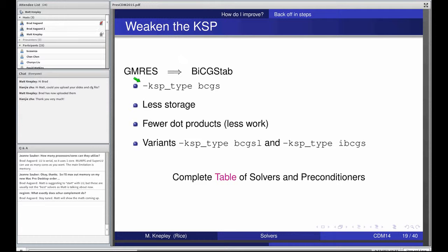And this is the idea behind our use of solvers. There is no solver code in PyLith. There is one line that says KSP solve, and then all of the solvers and preconditioners and hierarchical preconditioners and composed solvers, the entire thing is set up from the command line, even when we have multiple fields and when we have interacting solvers.